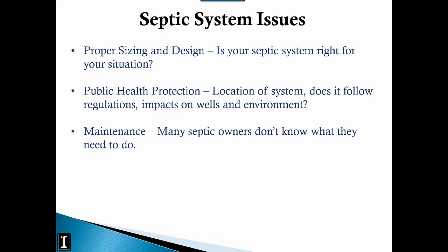Really, it's about public health protection. As far as the location, these days we're fortunate to have enough rules in place around the country that folks like Jim, when he was working for the health department, are inspecting the plans for a new home and where a septic system is going to go in, and they're signing off on that to make sure that the well's in the right place, the neighbor's well isn't too close, and that there's a plan for trying to minimize the risk of the drain field or anything coming from the septic contaminating a well.